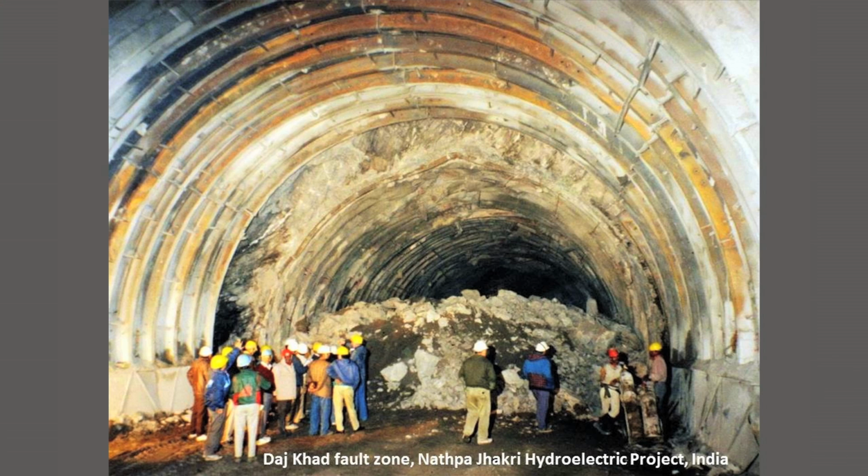And in general, the tunneling was good, but they reached one area where there was a known very large fault. And as they approached the fault, the ground got worse and worse, so they started installing steel sets. And finally, they got into the fault proper, and they simply could not control it. You can see here the sets have been severely deformed. There's about a meter of displacement, and the tunnel is clearly unstable, not acceptable.